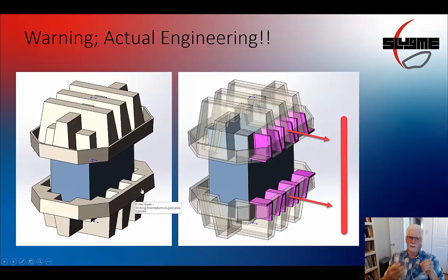And when I say protect the part, you want to keep the G-forces down. So this pulp is actually going to be somewhat springy. So just like if it was foam or something like that, it's going to have some spring to it. And so when it slams against the wall, let's say you dropped it straight on the concrete, 36 inches onto concrete, and the part is trying to crush the pulp, and the pulp is compressing, and you need to know how many ribs to put around this thing to make sure it doesn't overcompress or undercompress.